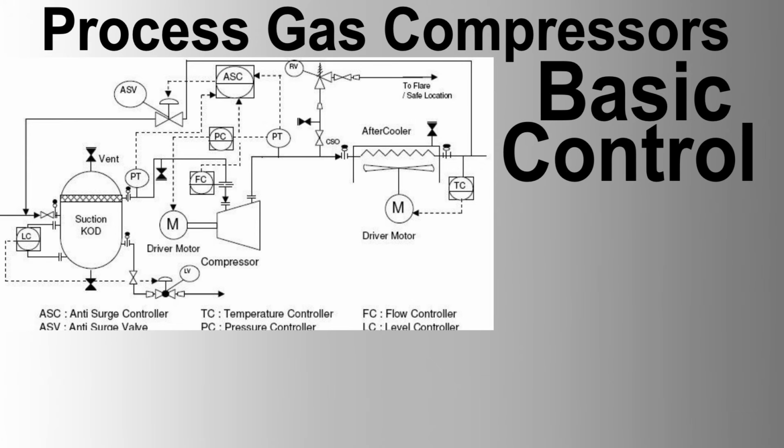Maintenance and monitoring. Regular inspections: routine inspections and maintenance of VFDs, compressors, and associated instrumentation ensure reliable operation. Condition monitoring: continuous monitoring systems can detect early signs of wear or failure, allowing for proactive maintenance. This detailed process description outlines the role and operation of VFD-driven LP, MP, and HP process gas compressors in an upstream crude oil processing facility, highlighting the integration of VFD technology for enhanced control and efficiency.